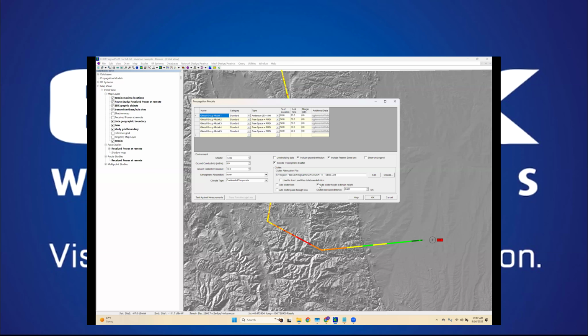However, this is not the method that gets used in traditional land mobile radio. And so if you're coming from a land mobile planning space and want to look at ACARS ground to air communications, it would be really important that first we make sure that we're treating the clutter appropriately, because typically in digital mobile radio, you'll use this add clutter loss method, which is just going to add additional loss for the clutter type at that location.